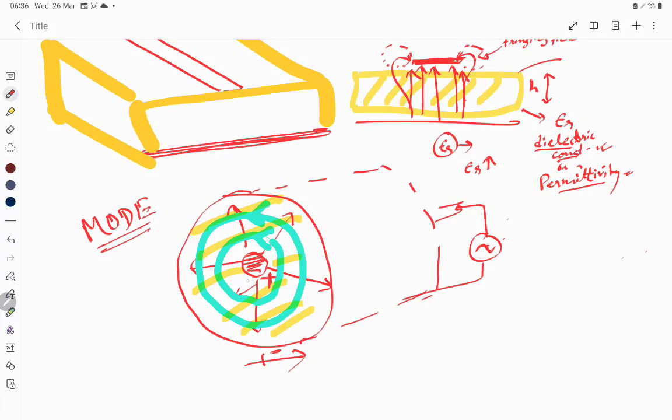So in this particular case, in this coaxial case, the electric field is coming out of the page, right? And the propagation of the signal is coming out of the page. That is the direction, and let us draw it here. So this is the direction of propagation of the signal, and your electric fields are all perpendicular or orthogonal to that direction, and your magnetic fields are also perpendicular to that direction.